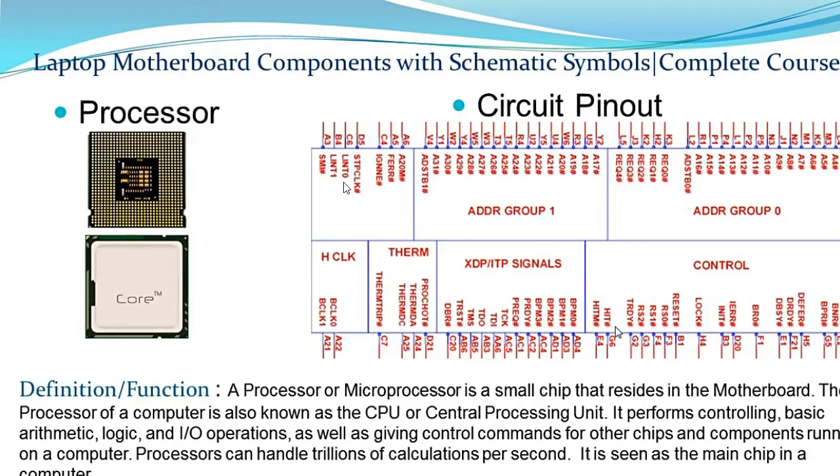Of course, you're going to find other controllers like the power controller, the logic controller, the arithmetic controller, etc. So basically the power for the CPU, we call it plus VCC core. Plus VCC core for CPUs is usually between 0.7 volts DC and 1.3 volts. And here of course all those are pinouts.